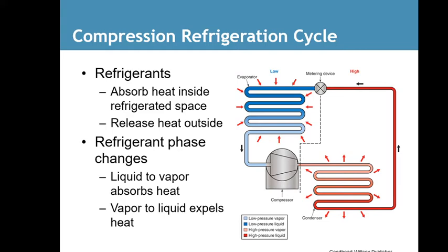When it goes into the evap coil, it's about 80% liquid, about 20% flash gas or vapor. As it works its way through the coil, there's a fan that assists it, that changes it from a liquid to a vapor. As it changes, it uses the heat in the home to make that change happen and takes the heat off the air that's passing through the coil. And then it goes through the suction line back to the compressor.